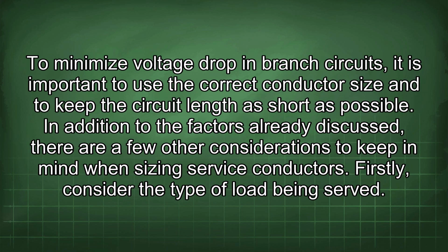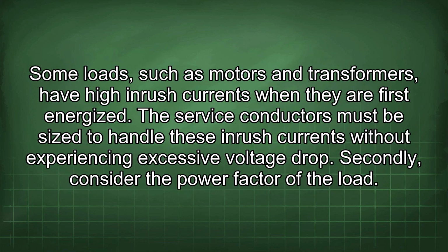To minimize voltage drop in branch circuits, it is important to use the correct conductor size and to keep the circuit length as short as possible. In addition to the factors already discussed, there are a few other considerations to keep in mind when sizing service conductors. Firstly, consider the type of load being served. Some loads, such as motors and transformers, have high inrush currents when they are first energized. The service conductors must be sized to handle these inrush currents without experiencing excessive voltage drop.